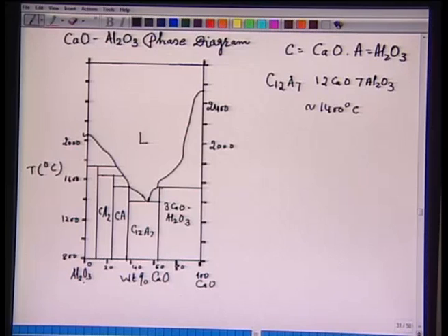So, it is attempted that by calcium injection a compound forms, 12CaO·7Al2O3, which has a very low melting point. In fact, it is liquid and it can be made to float also. That is the important point in the modification of alumina by calcium.